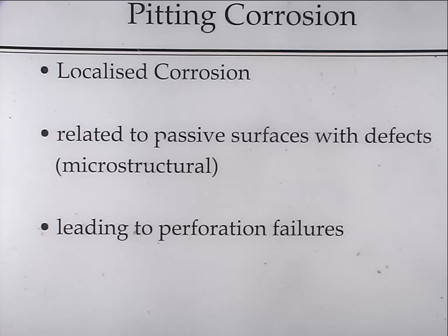So this is from a chemical plant, again a steel pipe, and this one, the attack is pretty well associated with the heat affected zone. There's a circumferential weld at both ends of this little section, and the pits, when you look at them, are all in a line almost running parallel to the weld, so the microstructure has had an influence as to where it decides to pit, and again ended up leaking, and that was that.